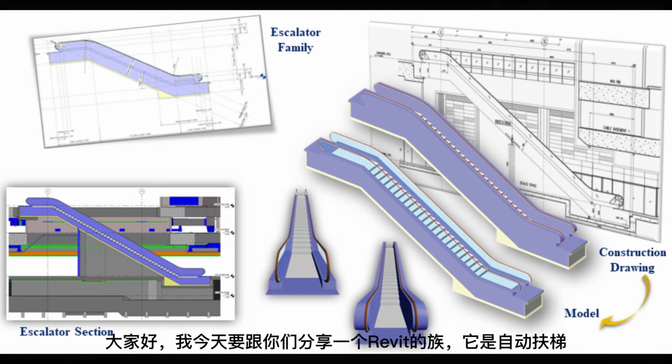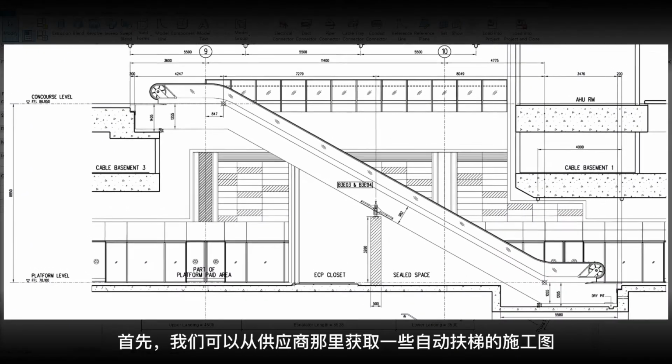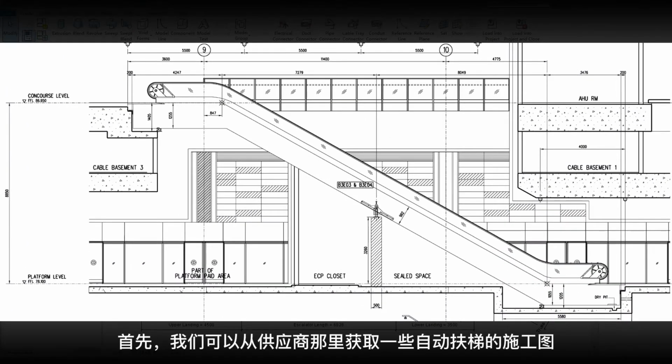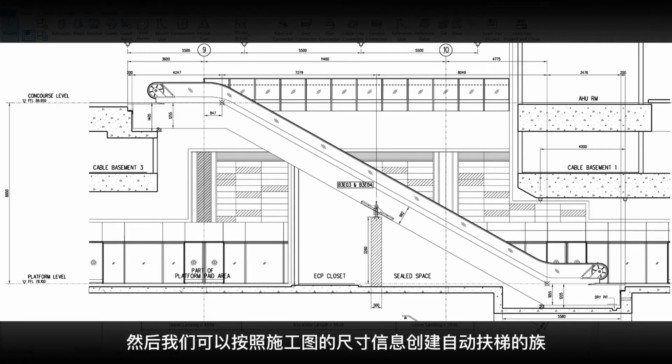This is the escalator family. At first, we can collect the escalator shop drawings from the supplier, like this elevation and the other plan and part detail shop drawings. Then, based on these shop drawings, we can create the escalator family.